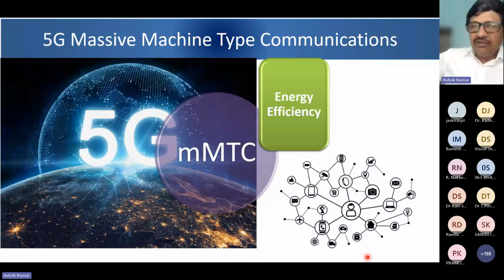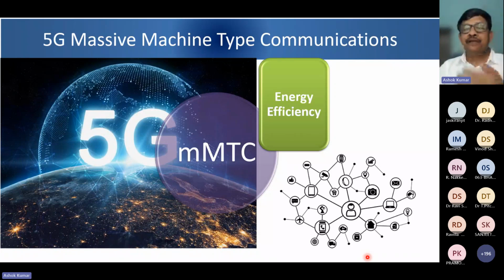That is one example. In 5G, there is a concept of bandwidth part wherein I can design IoT sensors with, say, only 5 megahertz channel bandwidth. I'm not required to build the sensor supporting the 400 megahertz channel bandwidth that 5G supports. So there are many things which have been done in 5G design to support energy efficiency of the base station and also energy efficiency of the devices, particularly the IoT sensors.